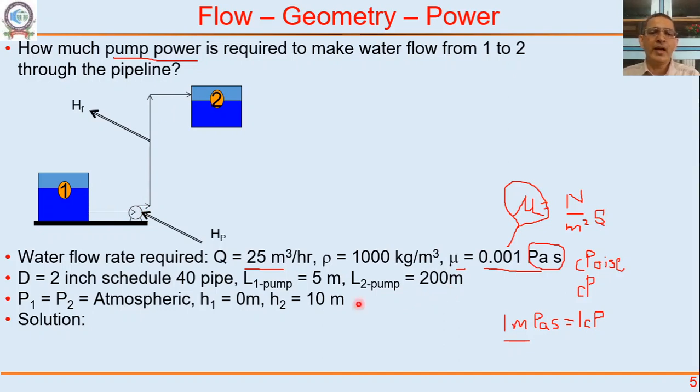Another question you may have is, this height difference is only 10 meters, then why do we require 205 meters of pipe? Okay. Because pipes are not directly connecting the 2 points. Pipe will go along the wall, maybe there is a balcony somewhere, maybe there is a parapet somewhere, so the pipe has to go around, maybe it has to go around one corner of the building and up through, so that it is not visible very nicely, it does not affect the aesthetics.